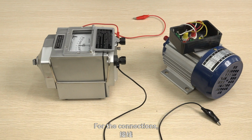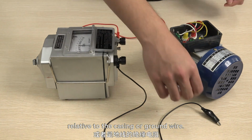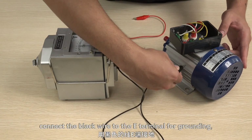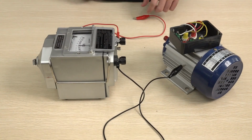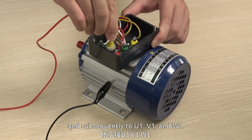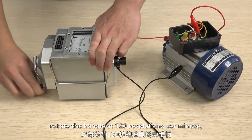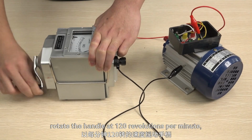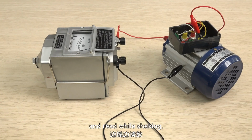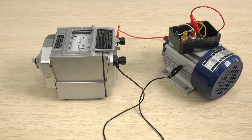For the connections, first measure the insulation resistance relative to the casing or ground wire. Generally, connect the casing terminal first. Connect the black wire to the E terminal for grounding. Then connect the red wire to the L terminal and subsequently to U1, V1, and W1. Then, slowly and then quickly, rotate the handle at 120 revolutions per minute, and take measurements for 1 minute, waiting for the pointer to stabilize. After reading, slowly detach the wires for discharging.